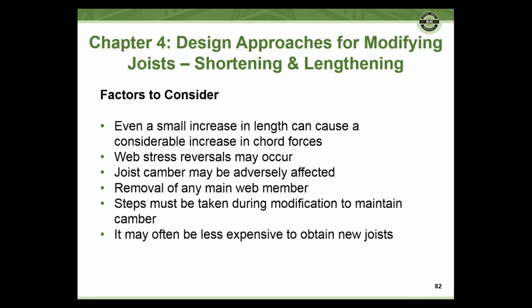In some cases, depending on how much you have to lengthen or shorten, it may be less expensive just to get a new joist. If you have to lengthen a joist by too much, a manufacturer will just recommend replacing the joist. Lengthening a joist 6 inches or a foot may not be too bad, but if you start getting longer than that, the manufacturer's probably going to recommend that you replace the joist.